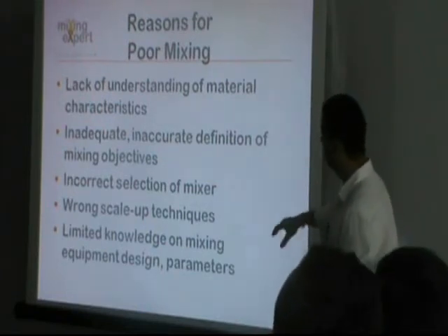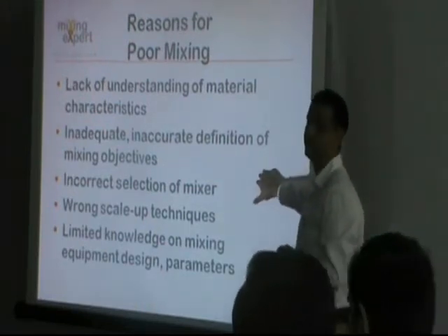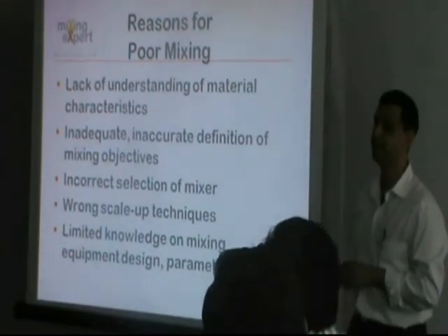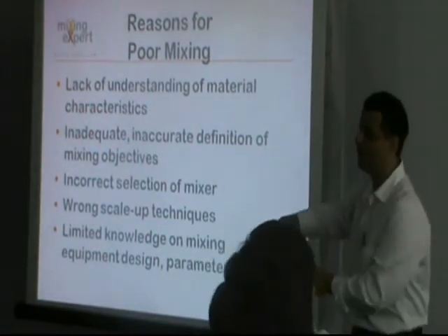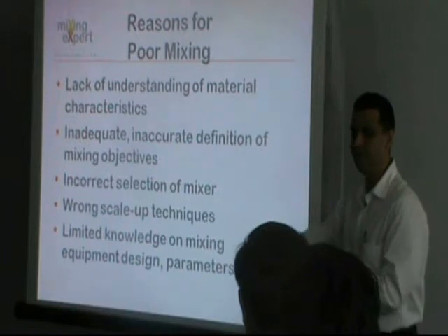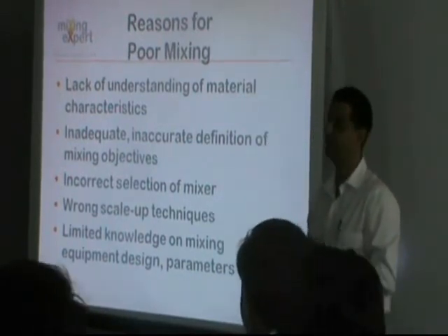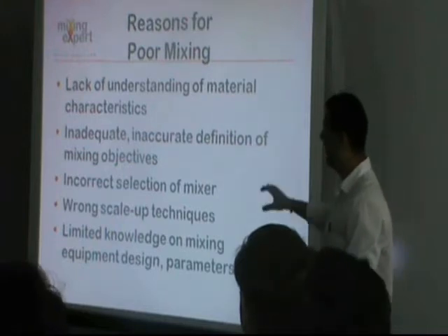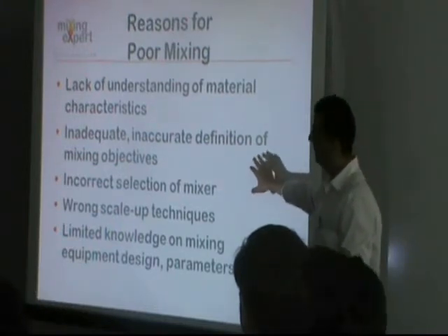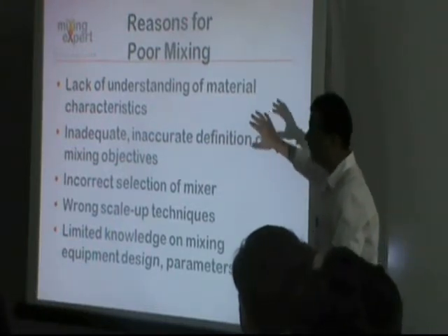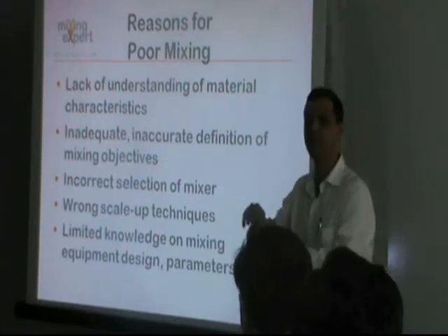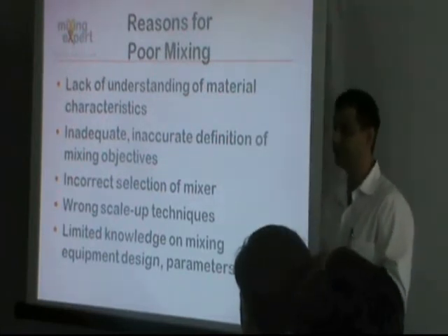The other thing is that the mixing objectives are not well defined. What is the end point of the mix? What are we trying to achieve? What is our desired state? A lot of times that is not accurately defined, and again it is somewhere due to lack of understanding of the product or the characteristics.